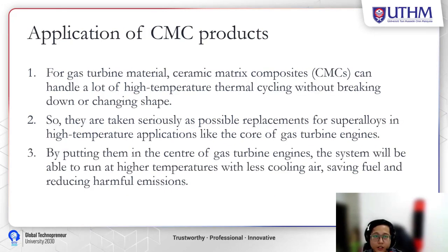For the application of CMC products for gas turbine materials, CMCs can handle a lot of high temperature thermal cycling without breaking down or changing shape. So they are being taken seriously as a possible replacement for superalloys in high temperature applications like the core of gas turbine engines.